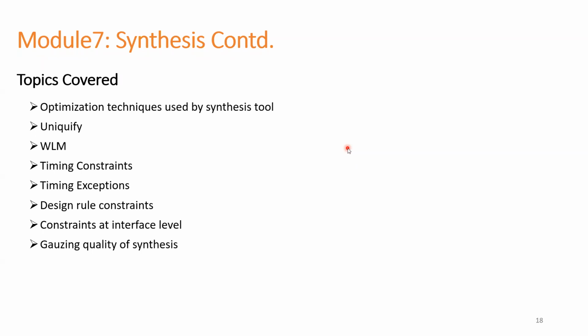And power aware also we can check. If there are any surprises, like power overshooting because of the used cell count, that also can be caught in synthesis itself. Post synthesis we can do power aware simulation, and area also we can check, how the quality is.